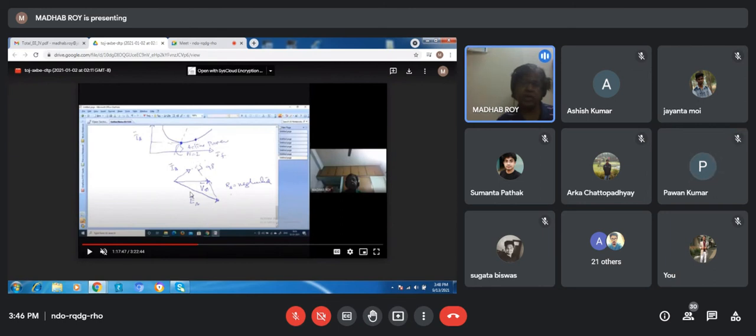So you can verify that this is a leading power factor load. The length of EA depends on the field current. Here the field current is high because the length of EA is large. If we go for further excitation, a further increase of the field current, then the current will increase. We can see that EA sin delta is constant. This is called the delta angle, and EA sin delta will be constant for constant power operation.